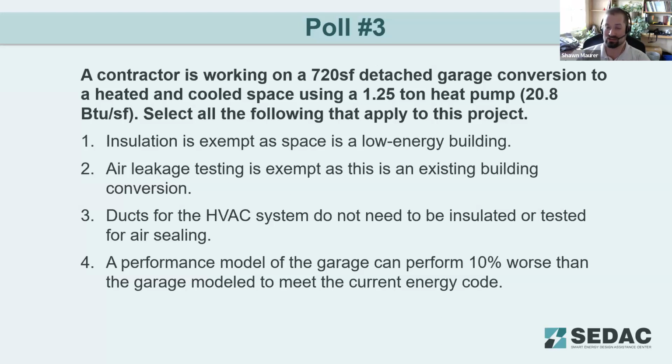So the addition itself must comply with new construction standards. The connecting portions of the building, like if you're doing a sunroom addition on a house, the wall between the sunroom and the existing house, if you alter that wall, it must comply with the alterations portion, which we'll touch on next. So it may require full compliance, may not, depending on the type of alteration. We'll touch on that.